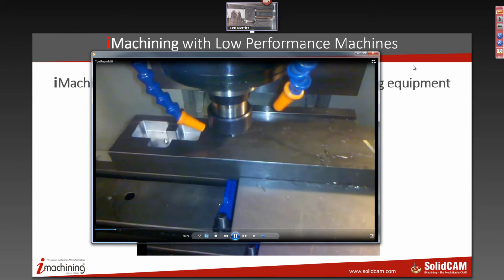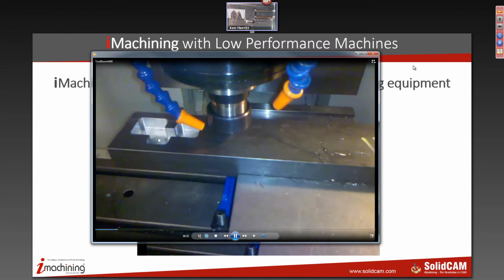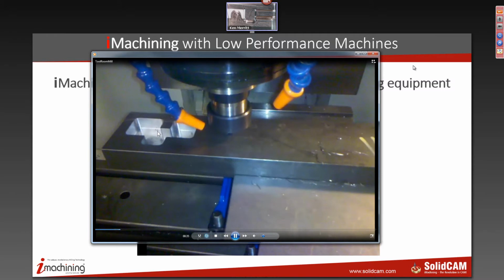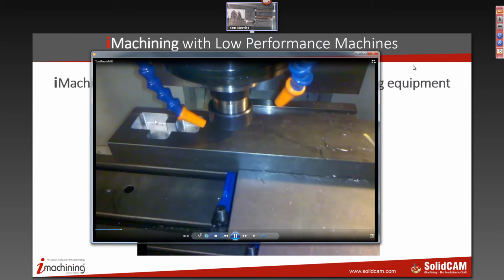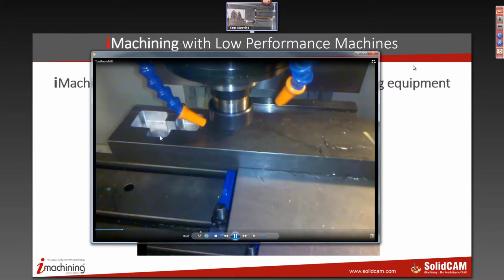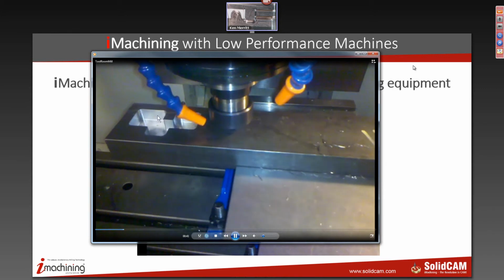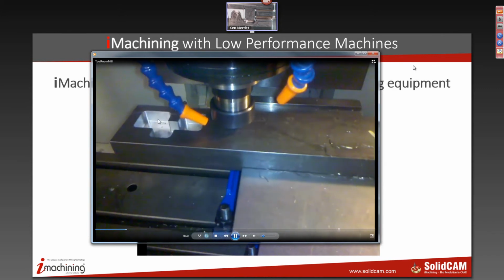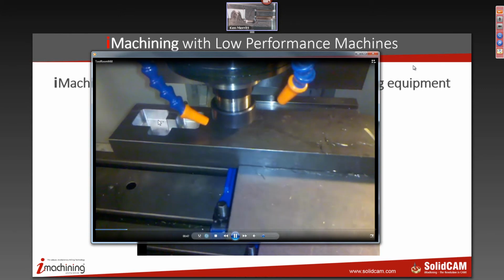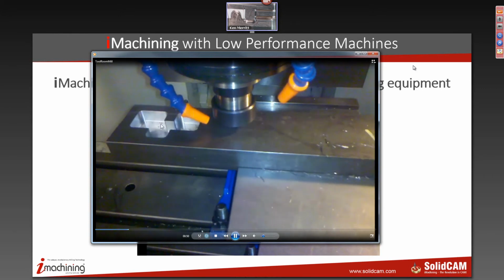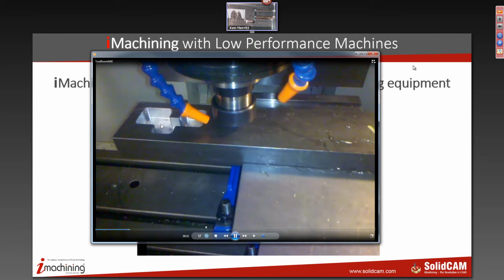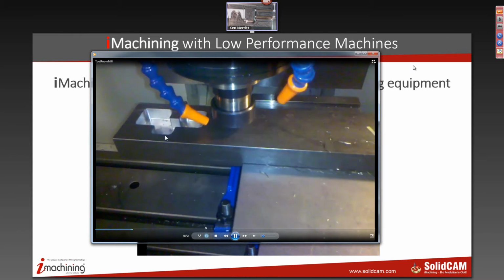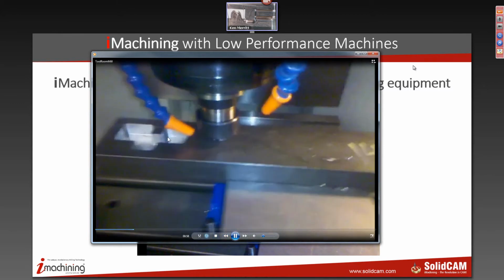This is a 1-inch deep pocket, approximately 3 inches by 2 inches or thereabouts. The user, one of our customers out in Colorado, was cutting this with a 3/8 inch tool, and he was taking 50,000 step downs at 2,200 RPM and 18 inches a minute. And that was about all the machine could take. It was vibrating it pretty bad. By the time he got to the bottom of this, 2 hours and 26 minutes worth of cutting, 50 step downs, the bottom 50 thou of that tool was gone.